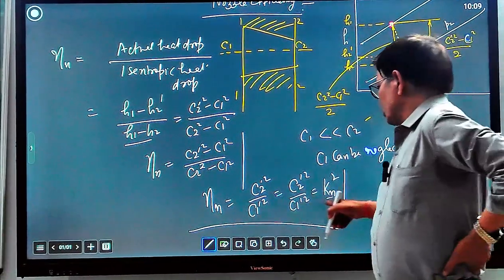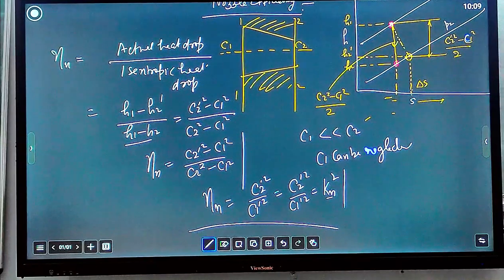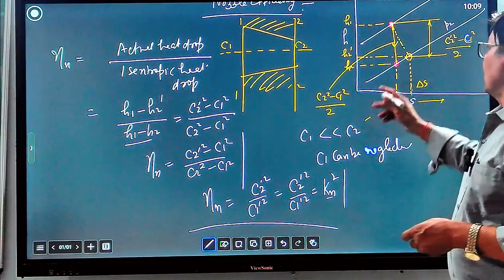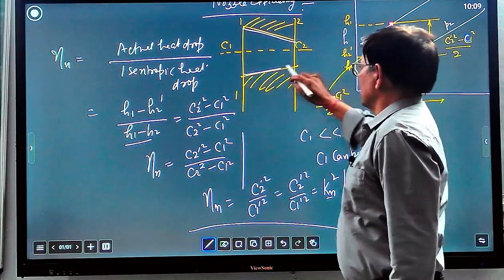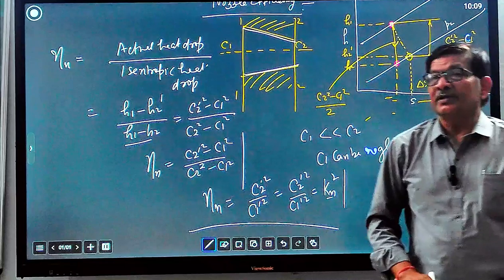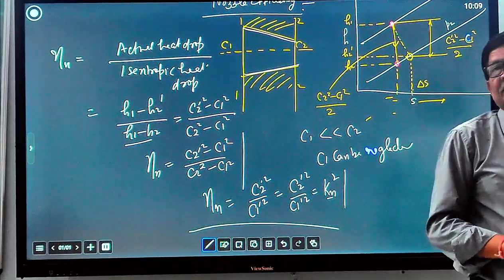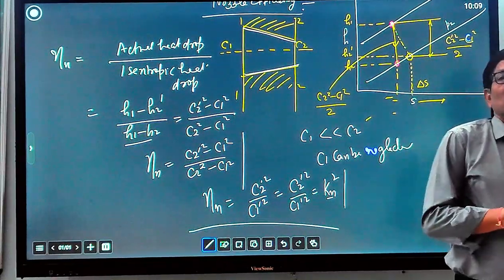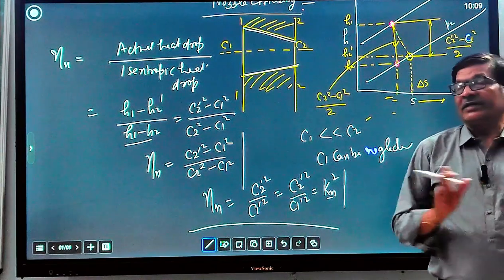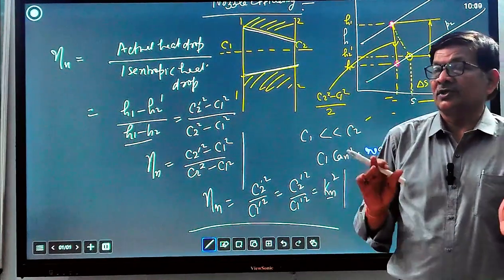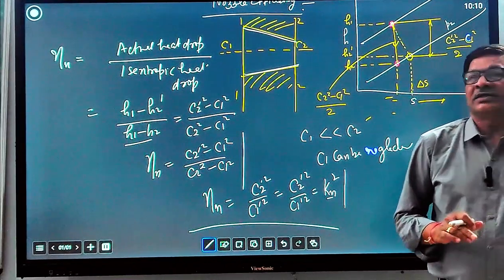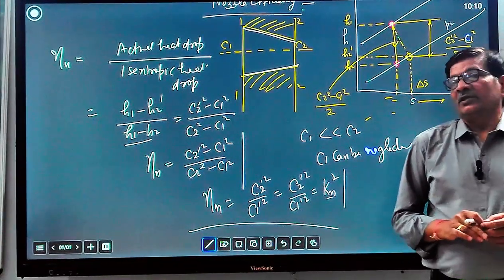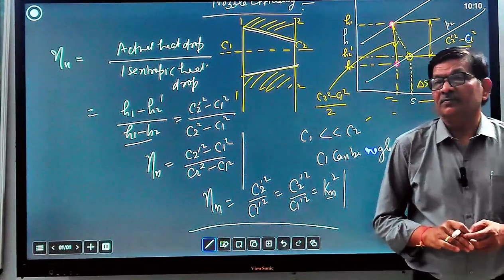This is known as the nozzle coefficient. And so how do we design a nozzle? This is only a convergent nozzle we have seen. Here you can see because it is converging, the chances of flow separation are almost nil. But in diverging, when the diameter of the flow passage is continuously increasing, the chances of separation are more. And if abrupt expansion takes place, then there is a chance the flow will separate from the surface.